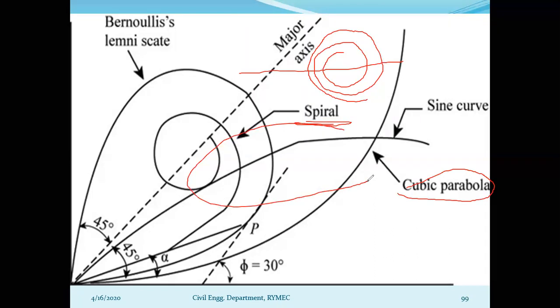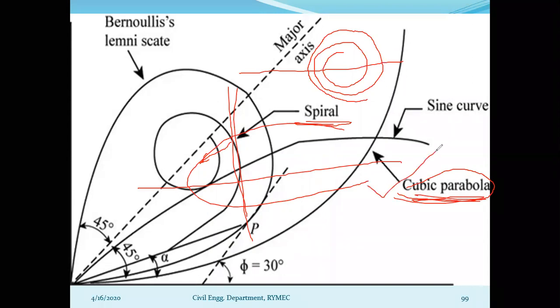So this type of curve also we can't provide in the valley curve, because see here, if you are going to cut in the vertical portion, this is your C. So when you are moving in this downward direction, definitely centrifugal force will increase. The centrifugal force increases, what did I tell you? You need to provide the cubic parabola again, which leads to discomfort to the road users.